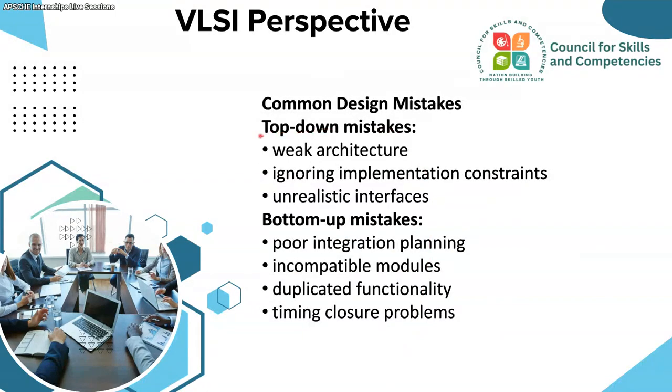In the top-down mistakes, when the architecture is weak, they ignore the implementation constraints and create unrealistic interfaces. Bottom-up mistakes mainly depend on integration planning: incompatible modules, duplicate functionality, and timing closure problems. These are the common design mistakes.